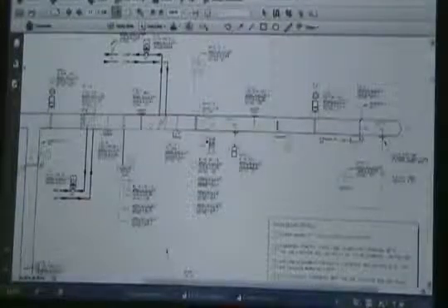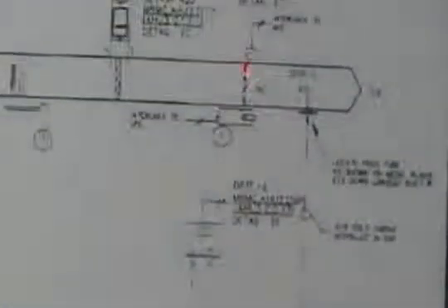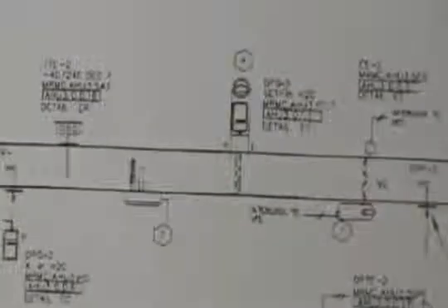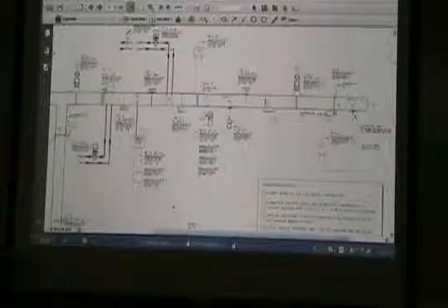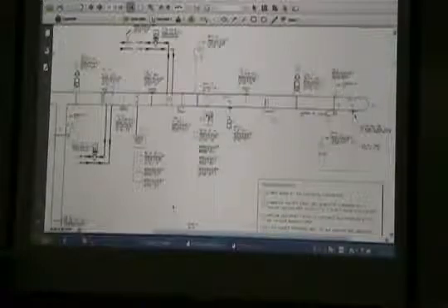Went through the smoke detectors that are wired back through the fire alarm system. We went through some of the damper operations, how the fan starts. The dampers are interrelated through programming so that the dampers are open before the fan starts. The differential pressure transmitter here is located probably up at our control cabinet with a field probe to maintain pressure in the duct. So we went back through the sequence of operation, which everybody's got a copy of.